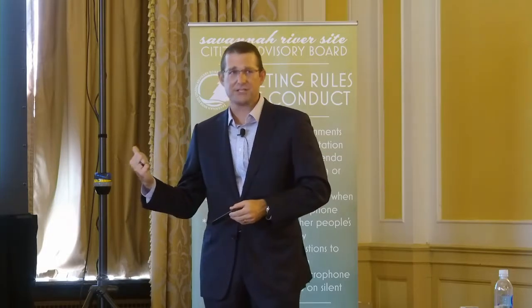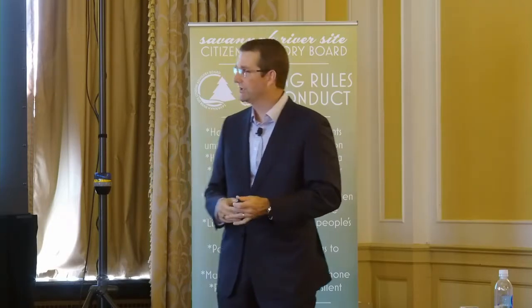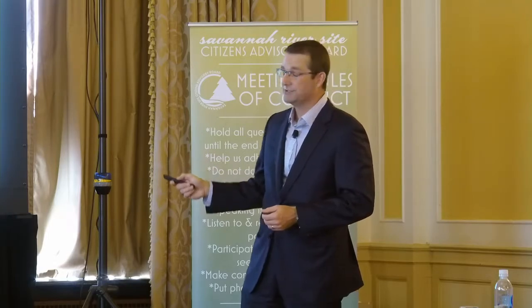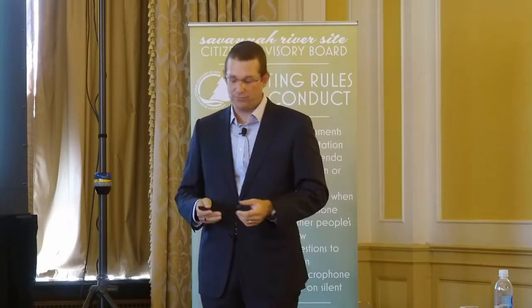But for our process, where it's going to go through a pump, where you're going to have a pressing shoe squeeze really hard into a rubber hose, something sharp is a risk. Now, we have, I think, expended every available effort to exclude those materials. We actually use magnetic separators. Every bit of dry material that's unloaded into our silos goes through a magnetic separator to try to remove as much foreign material as we can. But I don't think we can ever guarantee that you're never going to have foreign material in there.